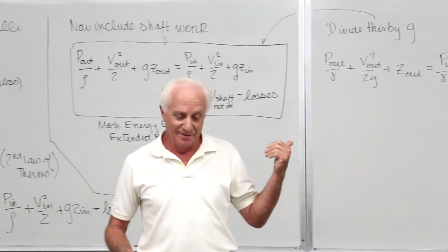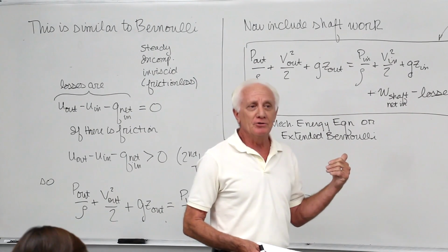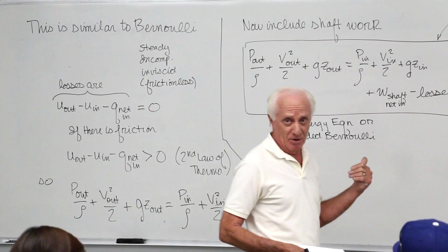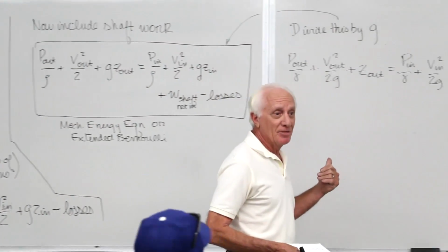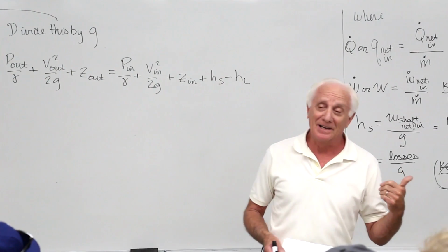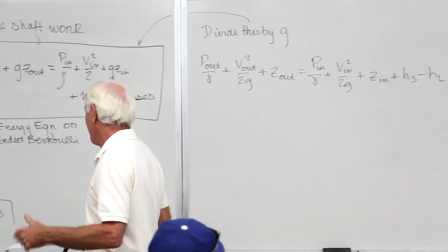You know, try and go to G sub C in English engineering. Go to G. Use pounds mass and pounds force. Oh, wow. Now we'll separate the knows from the don't knows. When do I divide by 32.2? When do I multiply by 32.2? You better know that, or it can get embarrassing. I guarantee you that. It can get downright embarrassing.